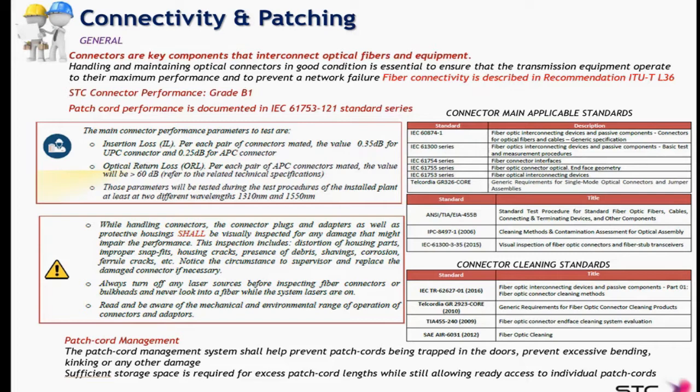The reflectance, the one in the grade B1, corresponds to at least 60 dB return loss. I will not insist enough on the fact that the connectors are the most critical piece of equipment in the outside plant. Please clean the connectors every single time.